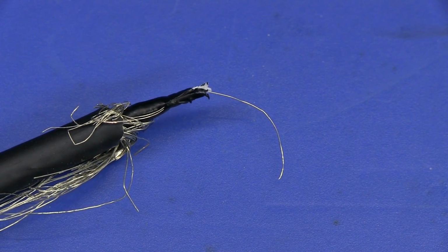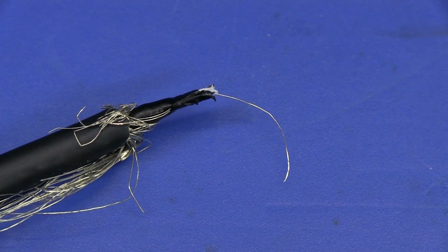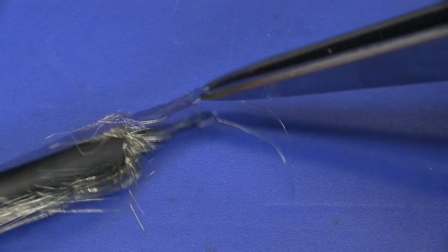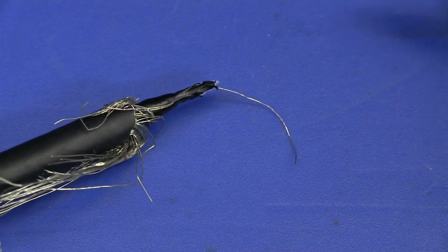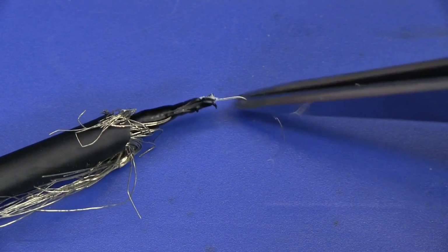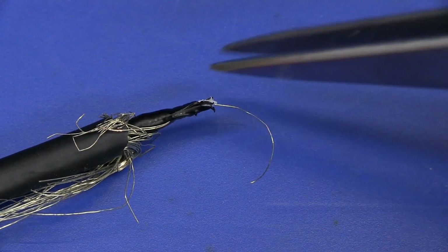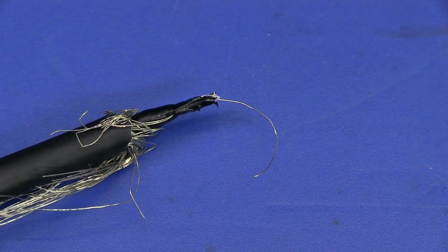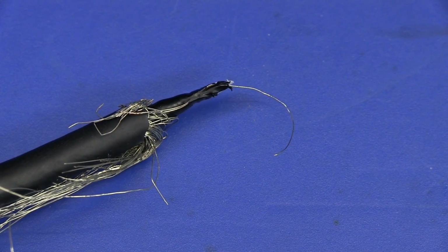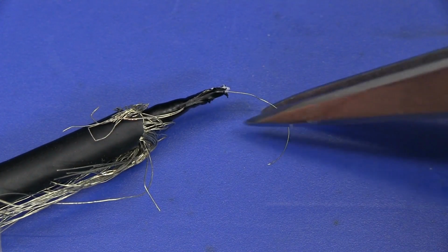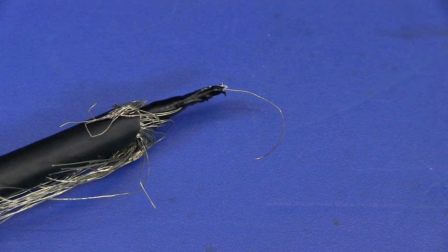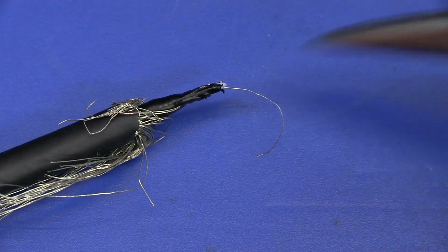You know, the actual DC resistance is important, but it's not the main driving factor. Transmission line design theory, I won't go into it. It is actually quite complex. I may have to do a separate video on this, actually simulating all this stuff and exactly how it works. But the lossy transmission line coax is optimized for the high bandwidth times 10 mode. So the times 1 mode is actually just a bit of a kludge added on, and that's why we're crippled with the low bandwidth on the times 1 mode, because they're trying to incorporate both features into a times 10 probe.